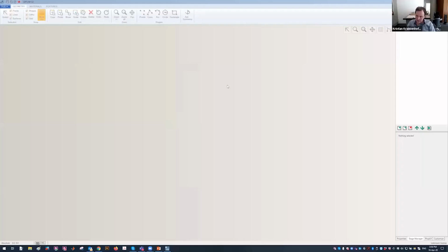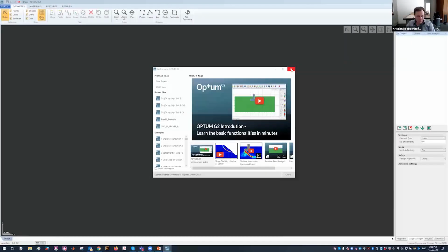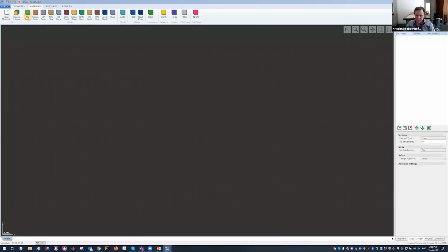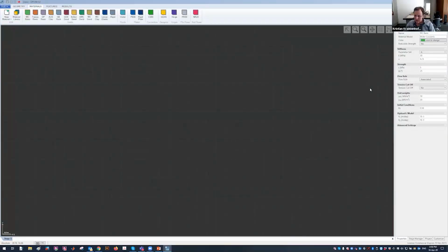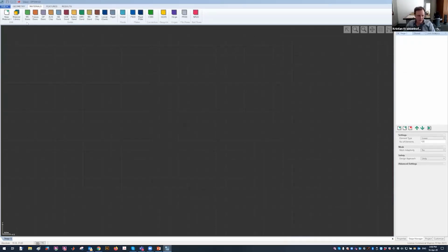But if you're interested in elastic anisotropy, which in some cases may be important as well, there is, in G2, we don't have it in G3 yet, but for all materials in G2, there is the possibility when it comes to the elastic law, we have these different parameter sets, A, B, and one called nonlinear, and then one called Graham-Holsby. That's this anisotropic model from these two guys, Graham and Holsby, which allows you to make a distinction between the Young's moduli in the two directions, vertically and horizontally. So that's what I can say about that.